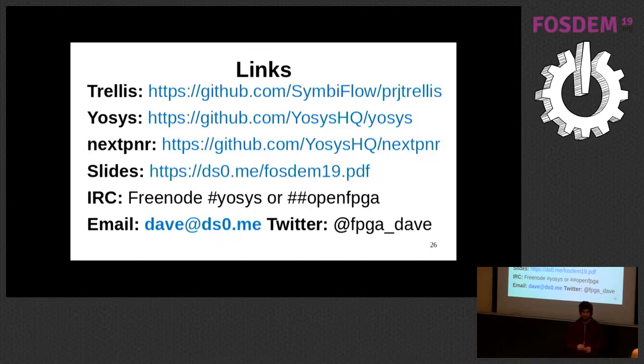Can you go the other way around? If you have a bitstream, can you get some RTL or Verilog? The answer is yes, we have a tool like that for the ICE40, Icebox Vlog, that goes from an ICE40 bitstream back to behavioral Verilog. I haven't actually finished doing something like that for the ECP5 yet, but it's entirely possible. It would just be a case of getting around to doing it.